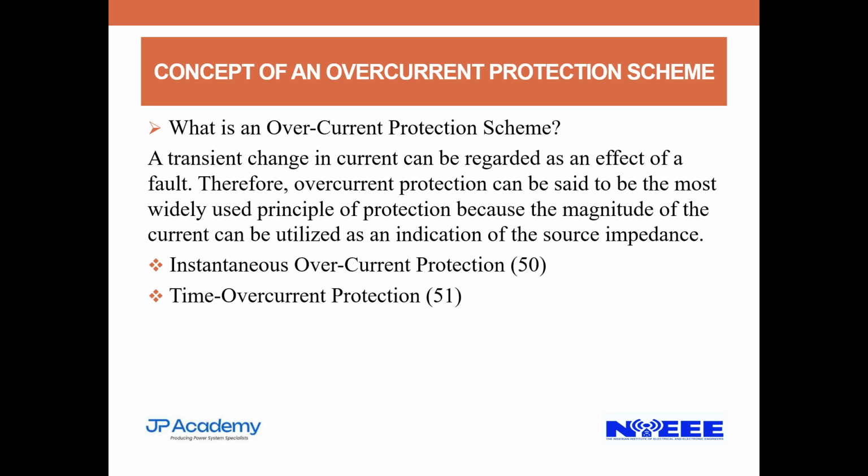Now, using our direct online starter, we are saying that as soon as this motor starts, the relay should issue a trip signal. So as the motor starts, the relay will turn off the motor. As the motor starts, the relay will open the breaker, isolating the motor. As the motor starts, the relay will do the same, and it will continue in that cycle.